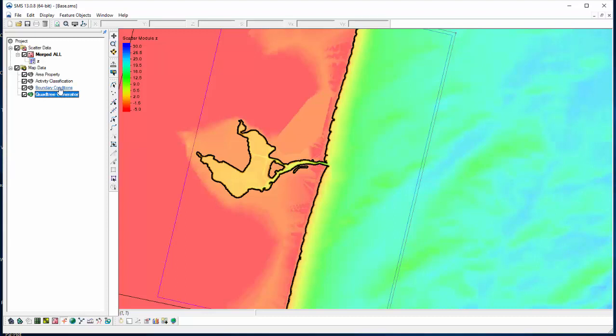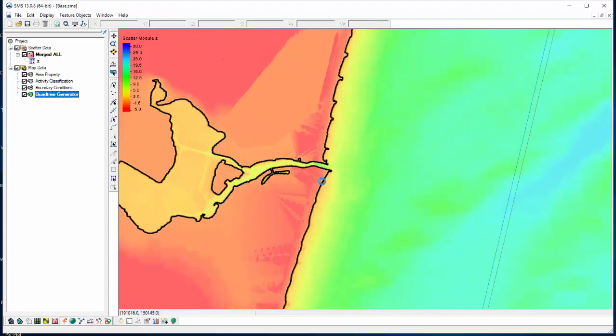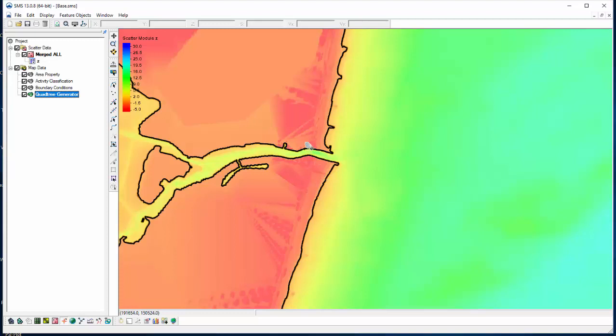All right. And so we still have our three different coverages that we need. But now we have a place to start for our areas of resolution. And so things to consider as we are adding resolution to areas are basically structures, that would be jetties and breakwaters and groins and things like that. You really need some resolution to define the flow around these structures. And so that's one area to consider.